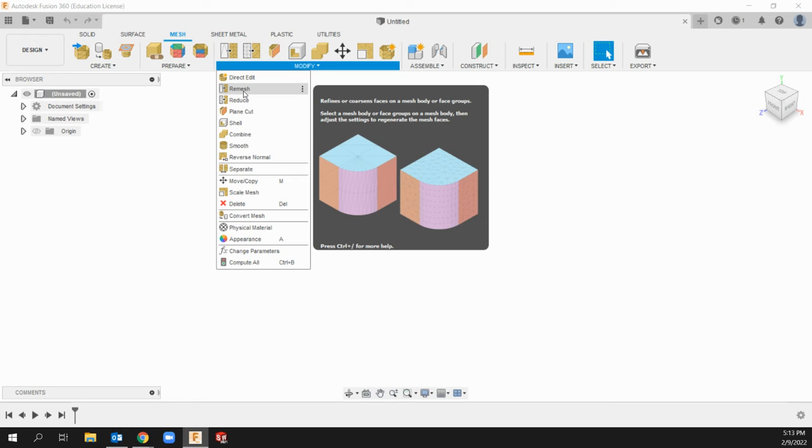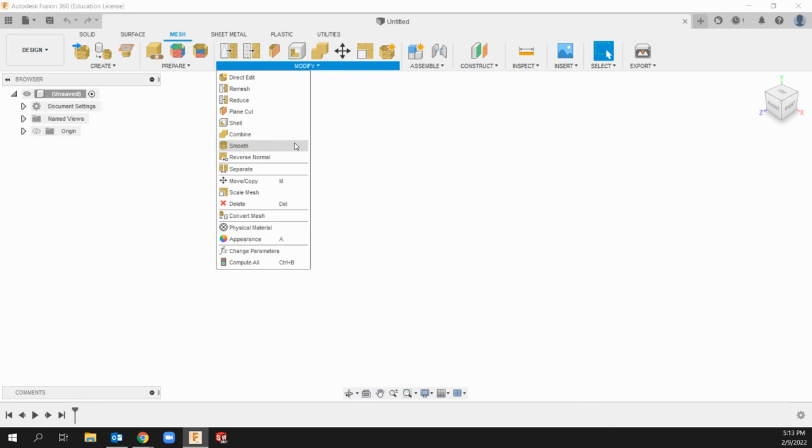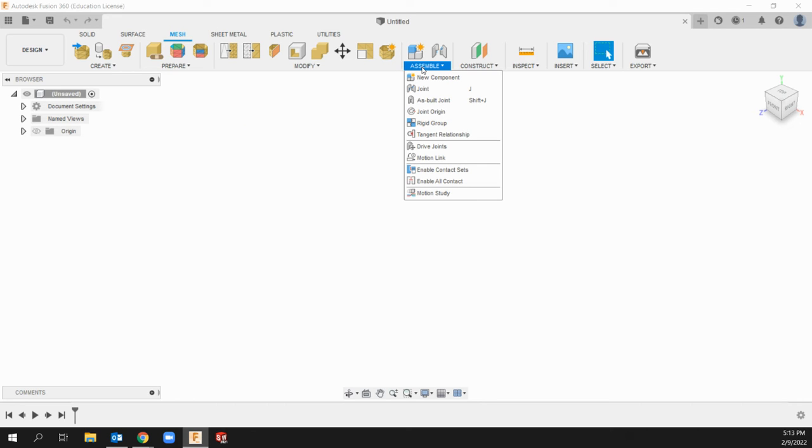It will blend if we have a high density mesh on a curved surface and then a really low fidelity mesh on a flat surface. When we remesh it, it will make sure that that is translated and blended nicely so that there's no irregular tessellation there.